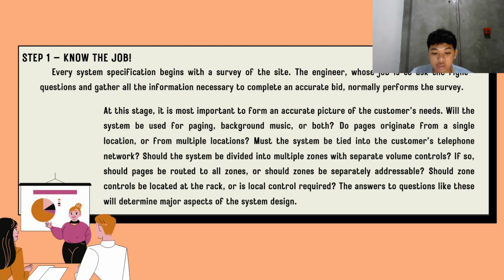What kinds of mounting surfaces will be encountered? And is the drop ceiling a lay-in type or tongue-in-groove? Where must cabling be routed? How accessible are those spaces? Are the partition walls and bearing members extended above the drop ceiling, where they may obstruct cable runs? And is conduit or plenum cable required? All of these factors directly affect the price quote and the actual task of the installation.